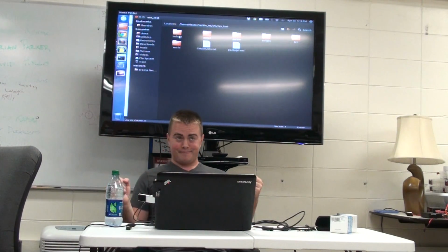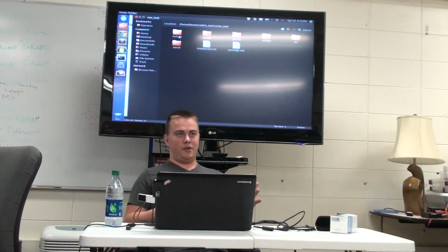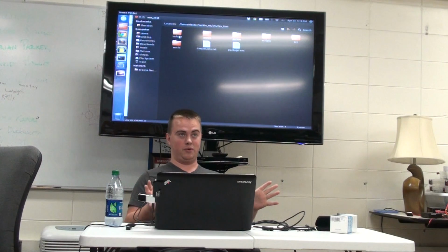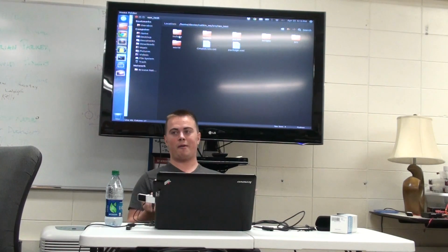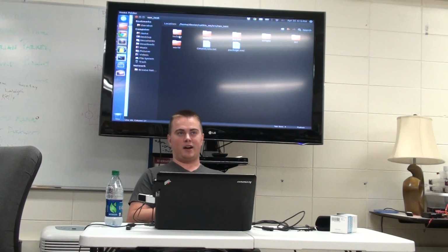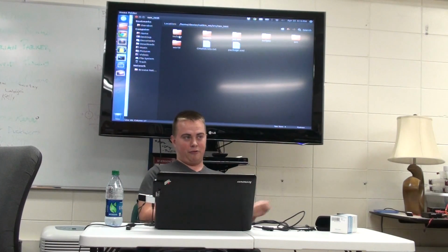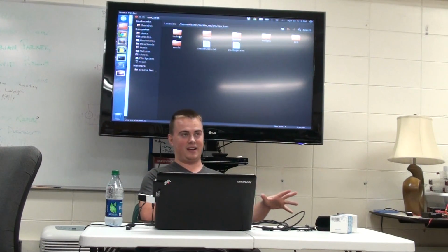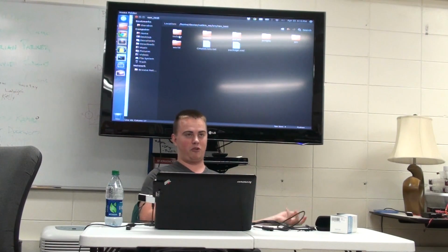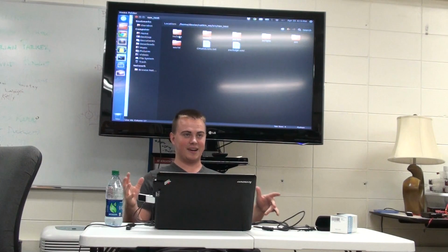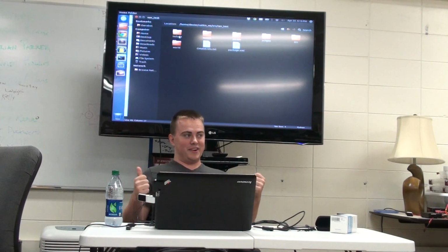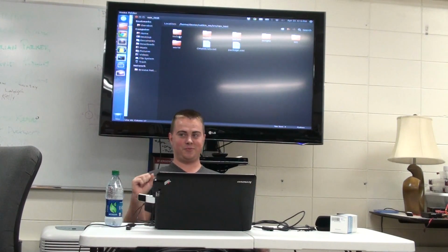The reason this is good is because it creates a uniform, homogeneous interface that you can use regardless of the robot. I was talking before about how typically for velocity, command velocity is the name of the topic, and for scans, scan or base scan is the name of the topic. The reason that's so is so I can write something like what we just wrote and plug it into one robot and have it run, or plug it into another robot and have it run exactly the same way, because all of the hardware specific things are happening in the bring up files and on the actual hardware itself, and my high level code is completely agnostic. So that's why it's good, and why you're typically never going to have just one file that you're launching.